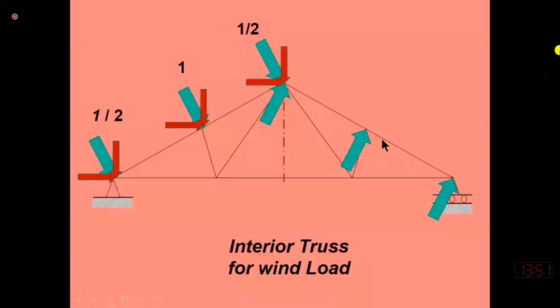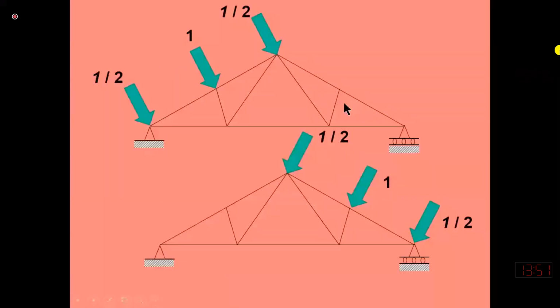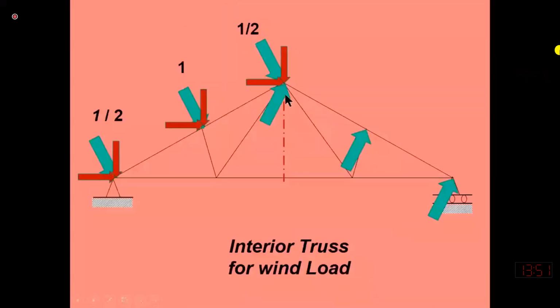So actually, we have already performed the wind load analysis for the leeward side. For example, in this case, if I multiply these forces by -1, then these forces will become this one. -1 means that it will become opposite. So you have already performed the leeward load analysis for this case.